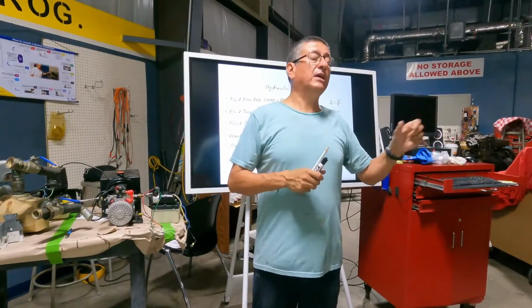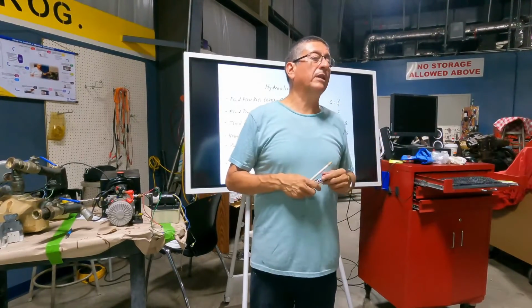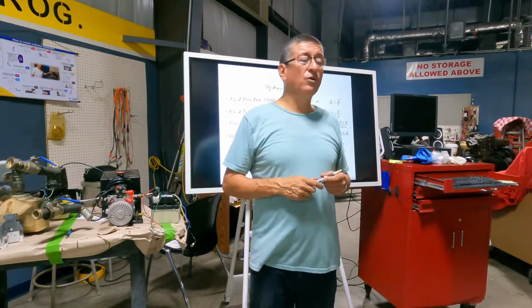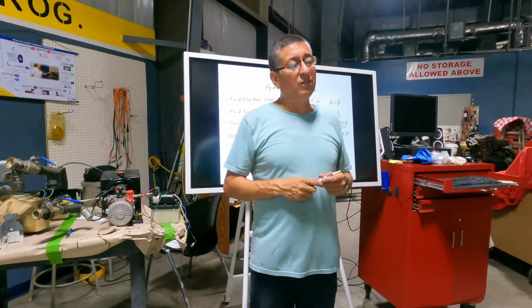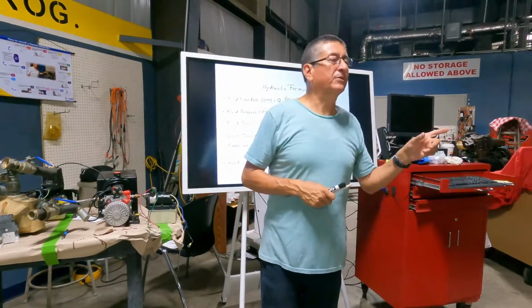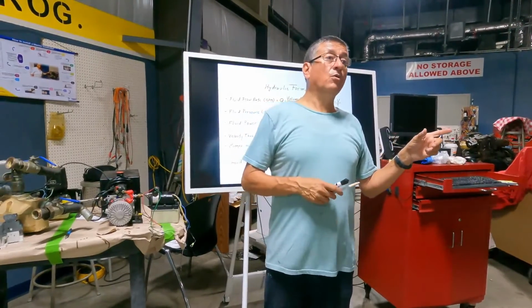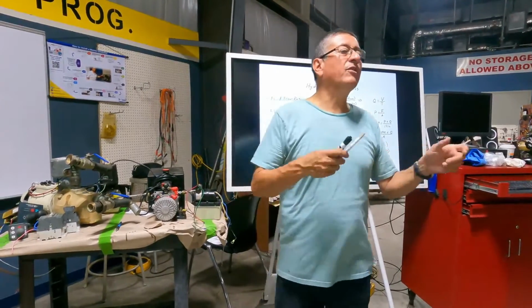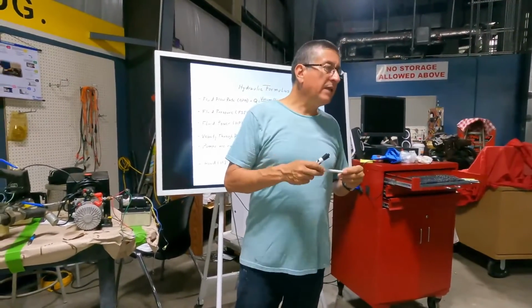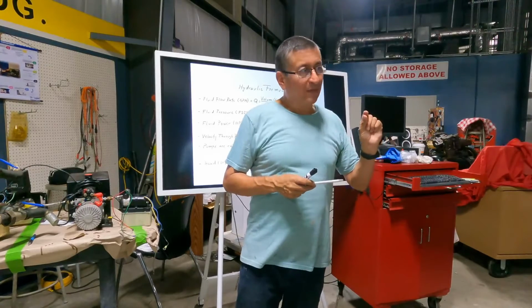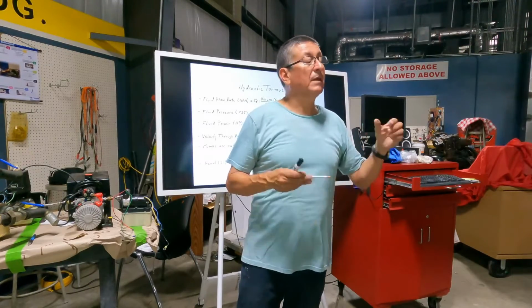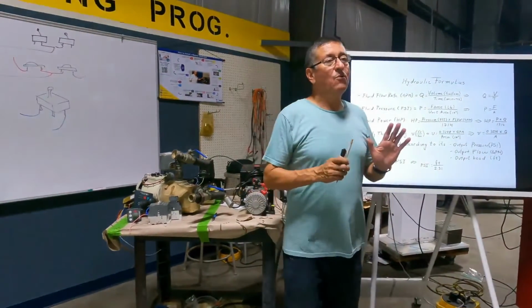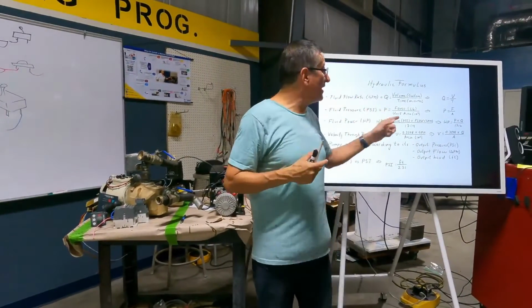For rigid lines, what do you recommend? Is it for hydraulic fluid, or for diesel, or for water? No, it's for diesel. Okay, this type of copper pipe is excellent. If it's for water, stainless steel. Depending on the fluid, they recommend the line, the thickness of the wall, and the material of the fittings. All right, good.